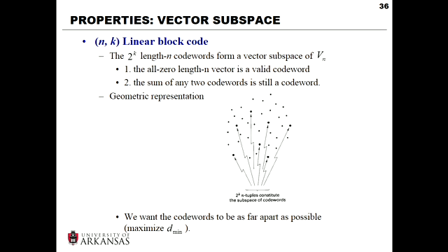It's using the special structure of the parity check matrix to do an iterative decoding. Its performance is very close to the optimal decoding, but it's still not as good as the optimal decoding. But optimal decoding is essentially impossible for LDPC code with k on the order of a few thousands. Okay, we can't do optimal decoding.